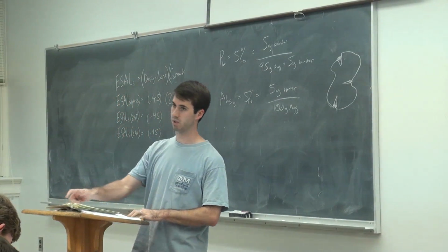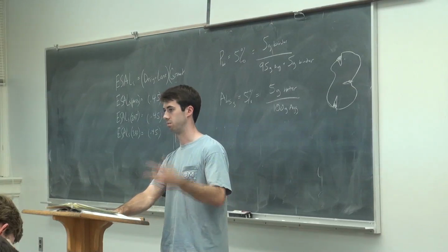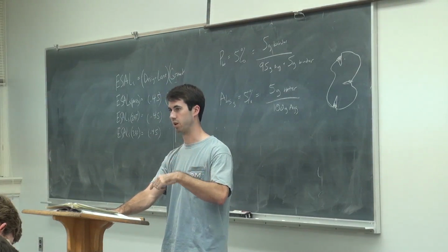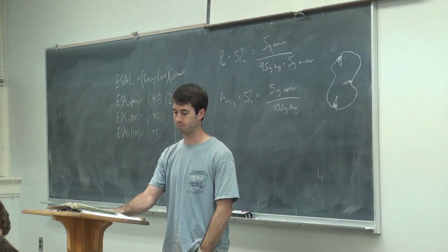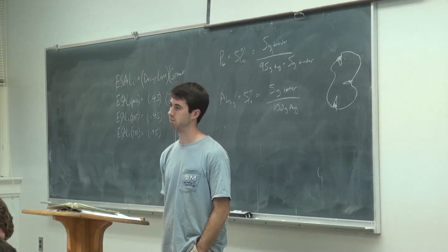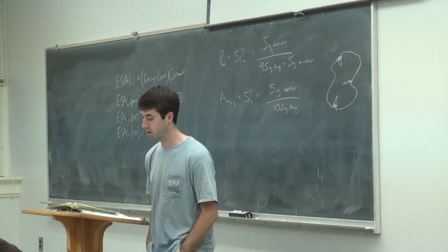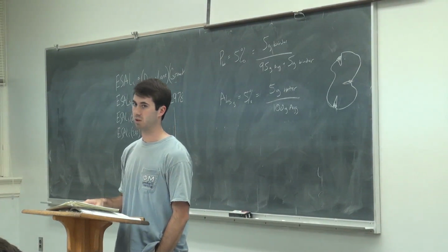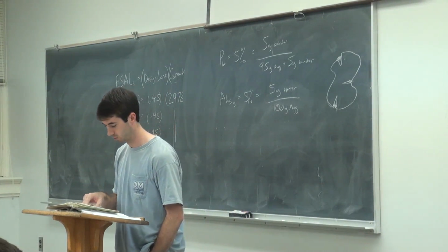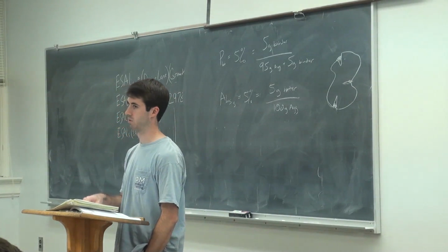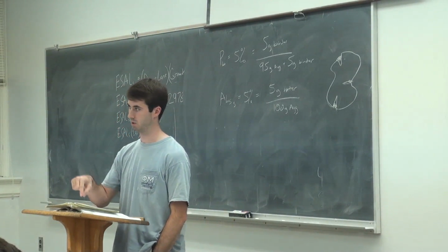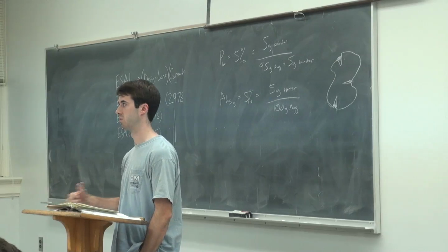The difference there is because they test at 10 degrees higher than what the actual spec is. There are some reasons for that, but just note that if they say grade a binder and you get -12 down here, it's not going to be a 64 minus 12. It's 64 minus 12 minus 10 more, so 64 minus 22.